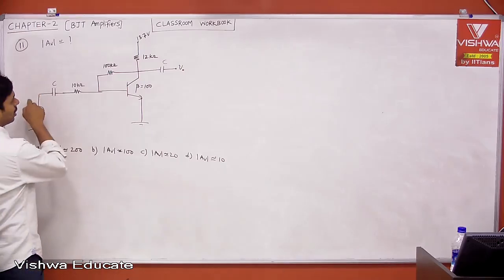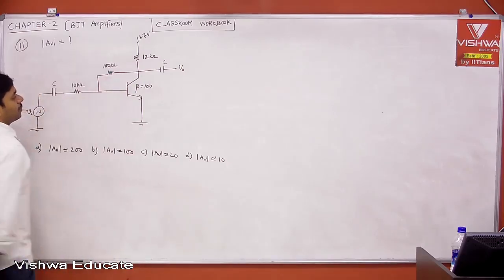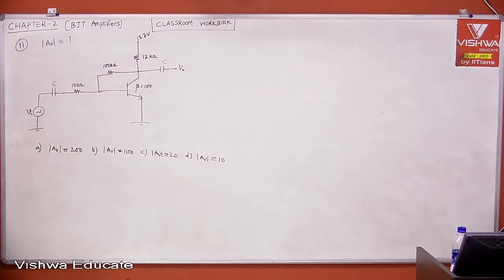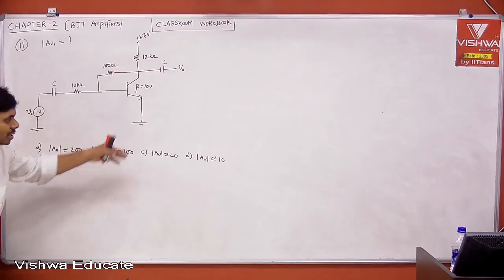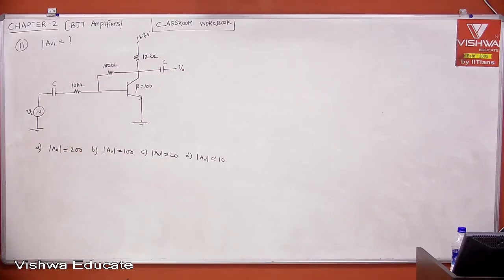And this is short circuit, right? And then 10K, 100K, 12K. Then just think about it. What is this configuration? It is a common emitter amplifier with feedback, which we did not see. We have seen CE with RE amplifier, where RE was providing negative feedback, that also we had seen, but this circuit we did not see, right? Just think how to calculate.